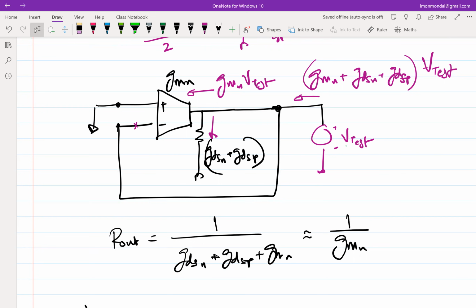But now we are closing the loop, and then we have to find this according to the effect of output impedance when you close the loop, right? So again, one of the assignments you did, finding out the output impedance when the loop is broken and when the loop is closed. So what was the conclusion? When the loop is closed, you have low impedance. Again, that makes sense because when negative feedback is working properly, you are not supposed to have any high impedance node.